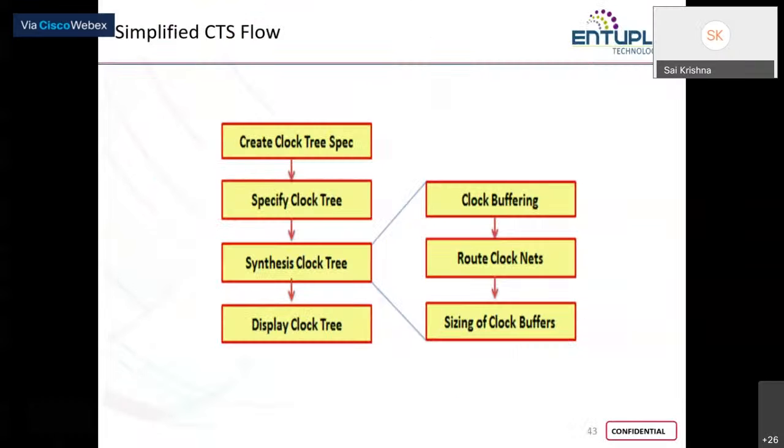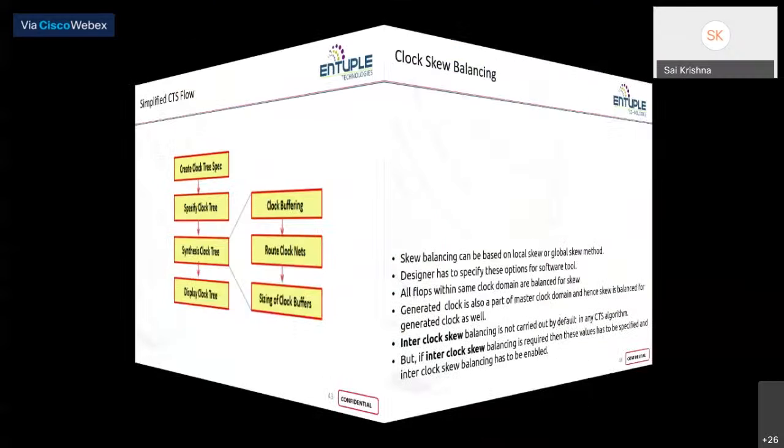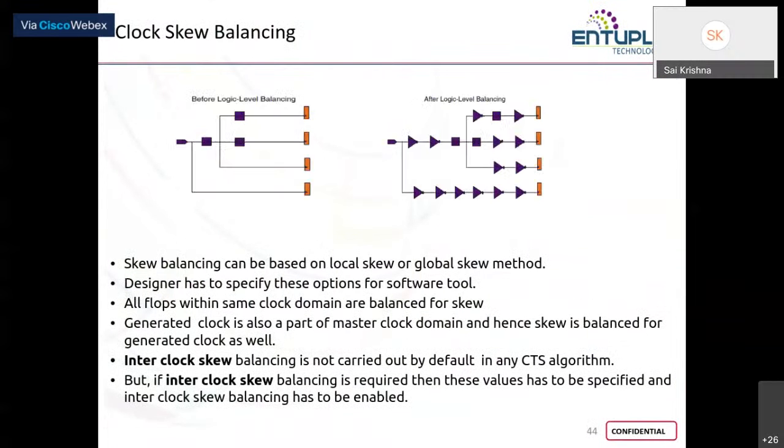So you first create a clock tree spec, load it along with your design, synthesize your clock tree, and then check for your insertion delays, skew, and also your timing reports. So that is all about your clock tree.